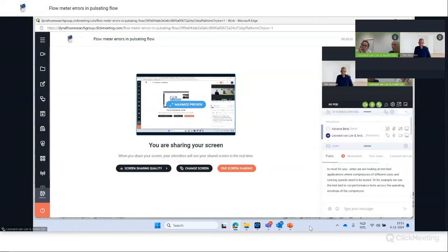For the rest, it depends on the frequency range. Well, the benefit of high frequencies is that you have a much shorter wavelength, so the attenuation of the acoustic waves is also much more rapid. So if you put a sensor further downstream, maybe with a buffer volume in between, that would be the best location to place your flow meter. So yeah, these are a few ideas, quite simple, but if you want to quantify it more, you need a simulation model to quantify the effects and know the target to make sure that you design according to the target.